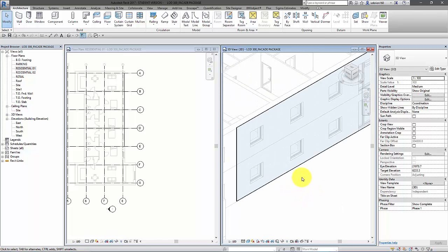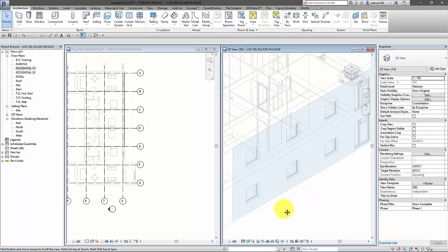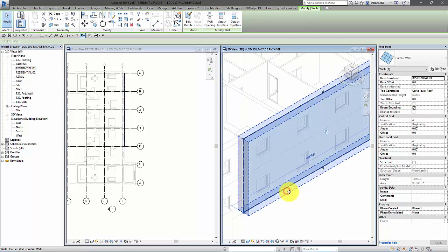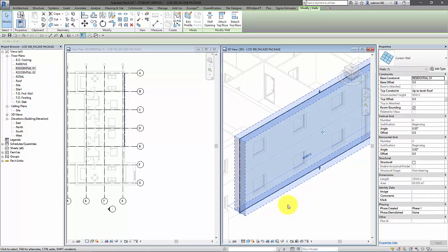So now we have the option to divide this up according to the paneling system that we want. Now, because we've made this according to a 300 millimeter module, I'm just going to start by dividing it up according to that 300 millimeter module. Because before, when you're doing it by hand, you can draw grids to do it. But remember, we have two types of grids here. We have the axial grid, which is this one here, which locates the main structural elements. But now we want to make a modular grid to locate the panels. So it's between the panels. We want the two things to line up together because grids are important.